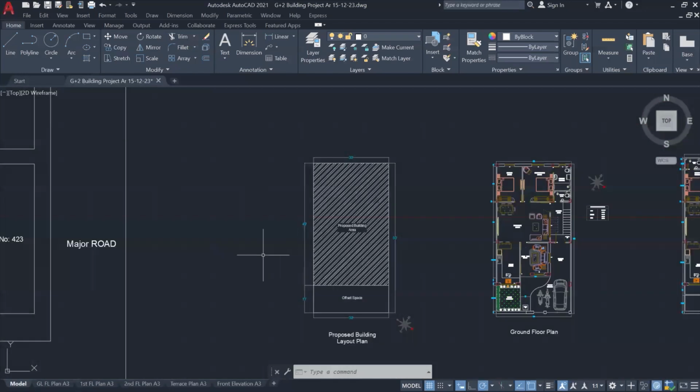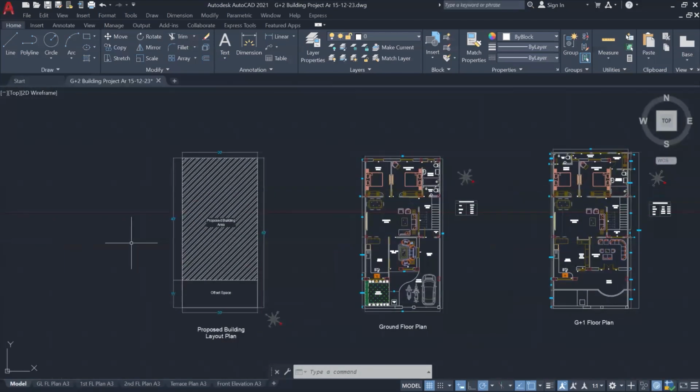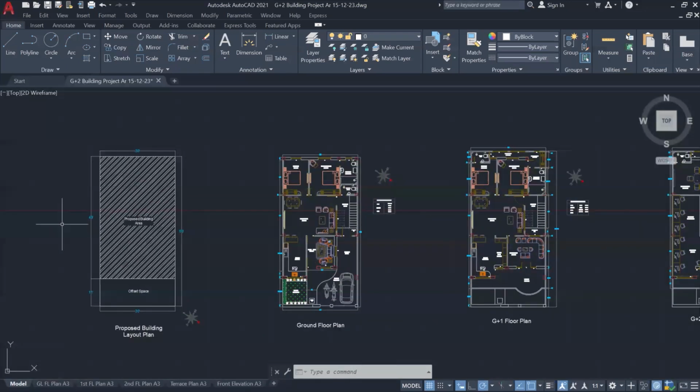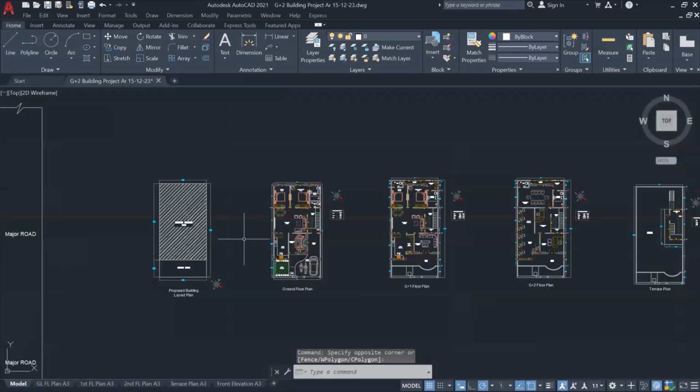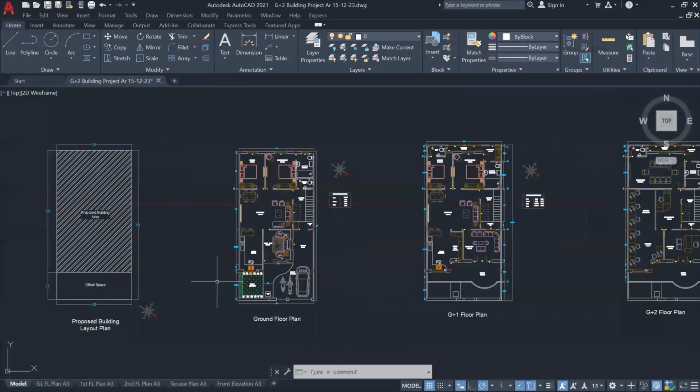And the second thing, left, right and back offsets are decided by what? The plot area of it. This is how we professionally go for it, and the actual dimensions, actual lengths will be in the Nagar Nigam or municipality PDFs. So you have to follow that PDF. Once the client and the authorities are okay with the offset plan, then we submit the architectural plan to the client.